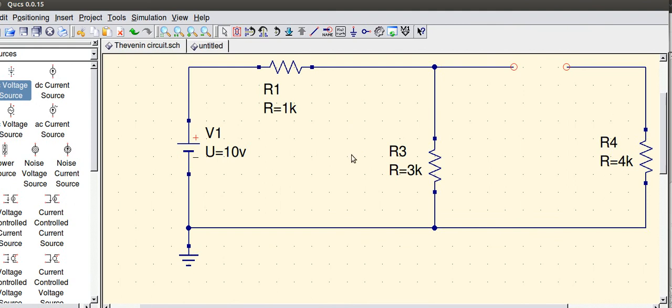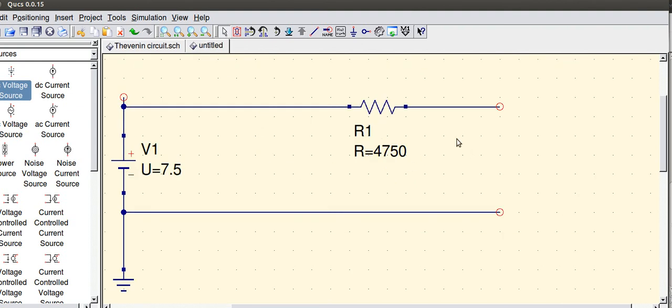Going back to my Thevenin circuit, what happens if it opens? I'll read a voltage drop across here, and who knows what it'll be. We already knew because we did it as part of the process. If I put my voltmeter across here, again, no current flow, no voltage drop, so the 7.5 would be what I would measure. That sort of gives you the open, infinite resistance, and zero resistance.